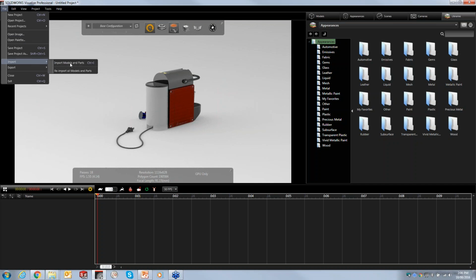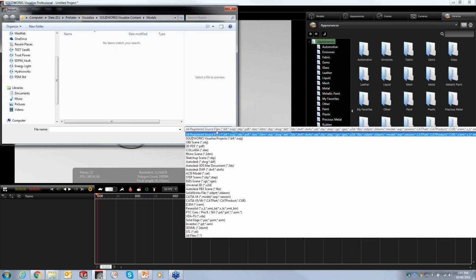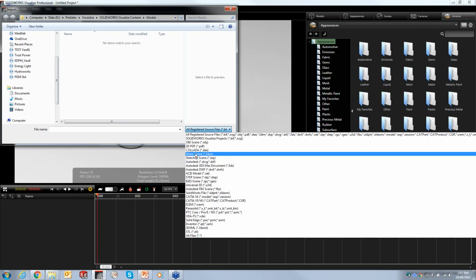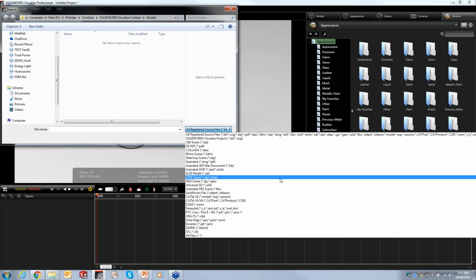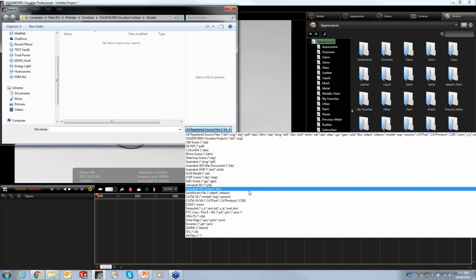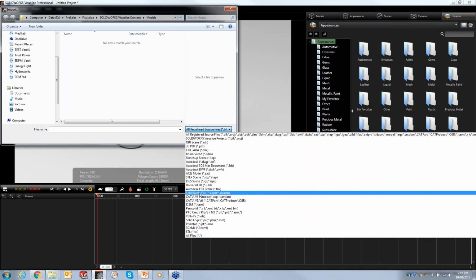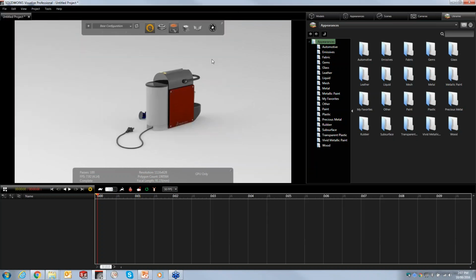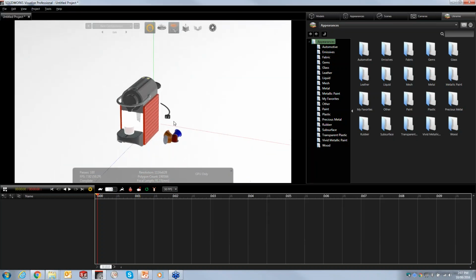importing geometry. We're going to take a quick look at the dialog box that shows us quite clearly many different file formats, and we can import models from multiple systems in at the same time. For example, we might have a layout of an office in SolidWorks. Maybe we downloaded some Rhino files, or in SolidWorks Visualize Professional, we can even import FBX files, and these can include pre-established animations from other software such as Maya or other formats. Okay, but we're going to work with just a SolidWorks file for today.